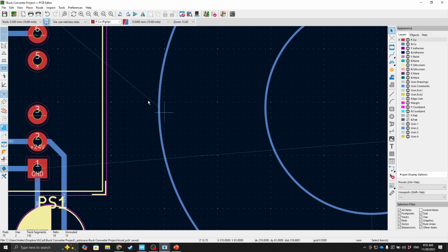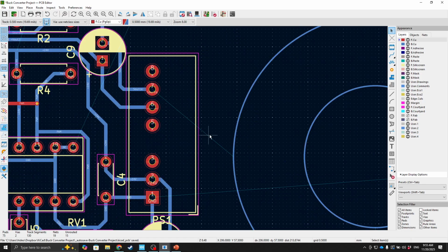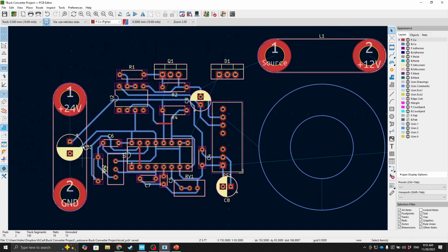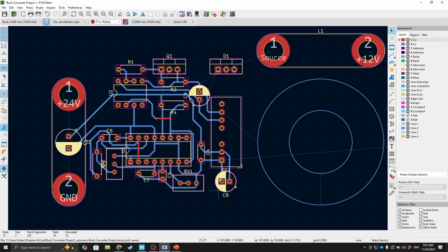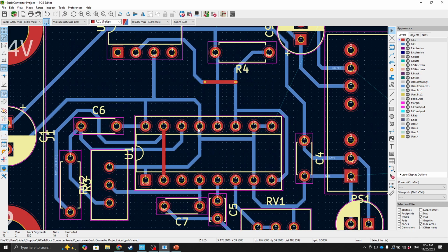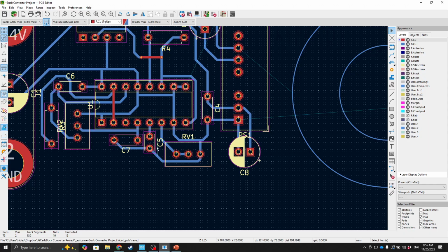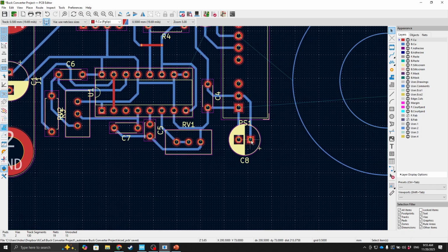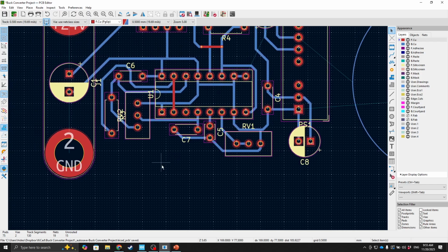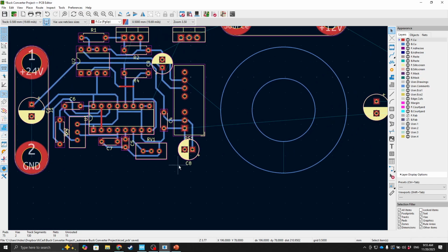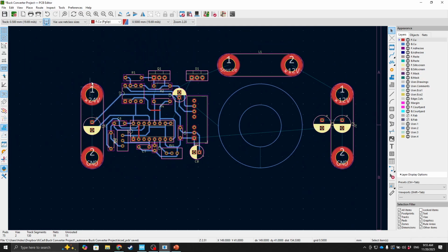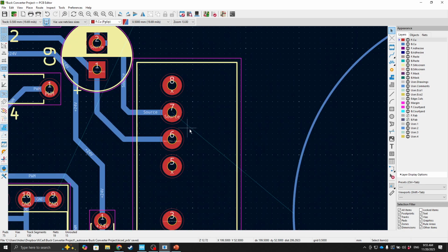And then you will think, why it didn't connect to this one? We don't make the ground connect to this ground, because I want to isolate the ground connection, not isolate it, but I want to differentiate the trace for the ground for the control, and then ground for the power circuit, I mean the trace that has the higher current flow.